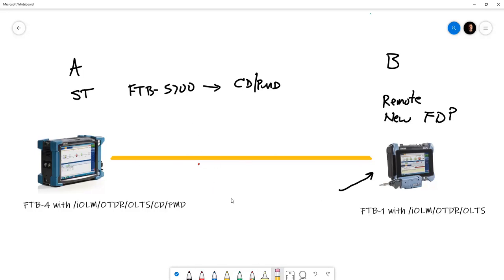You can leave and come back. The only test where you really need to do coupled testing, or where you have to have somebody on the far end or on both sides, is when you're doing OLTS. And so at some point you'll have to schedule that, but you'll do that at a specific time, right? And you also don't have to limit yourself to a much larger scope of time because you have to do all of the testing. And so this is what I mean by decoupled testing, rather, is you're able to test with more flexibility. And as you go through and do this different testing, you'll be able to work much more efficiently.